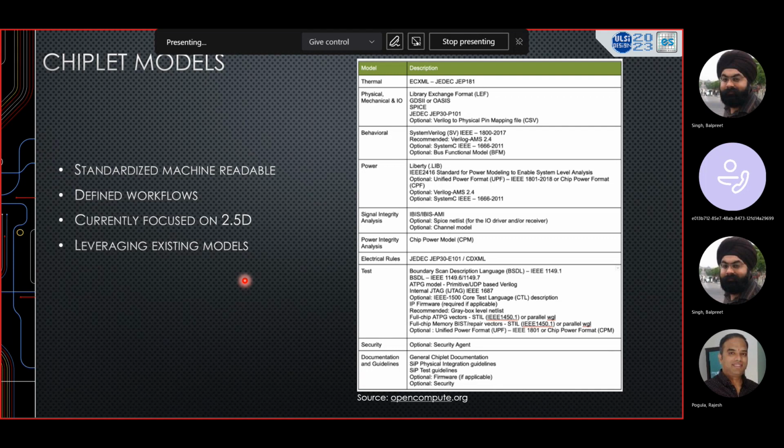Now, if you look at a 2.5D SoC, where I have two active dies at the top, and below I have just a connection in the die, but there's no device there. That people are calling 2.5D. But I think it depends on the definition you give. Someone was asking me during the break about one paper where there were some devices there, repeaters mainly. They still call it 2.5D, right? It depends on the person who's looking at it, right?